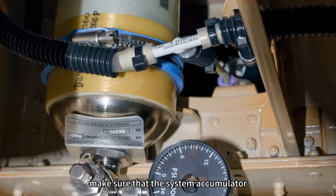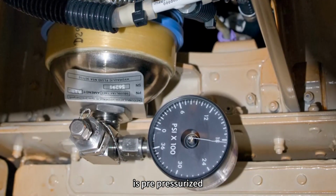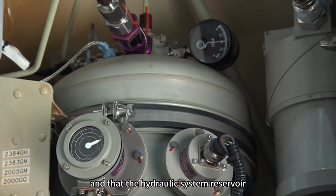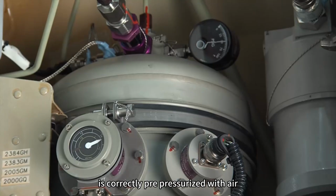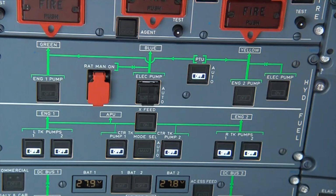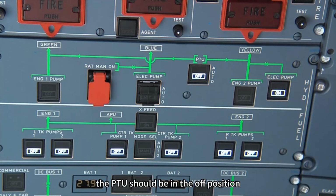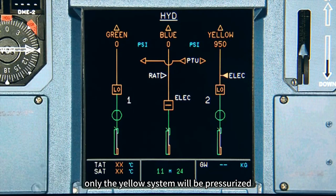Make sure that the system accumulator is pre-pressurized to the correct value and that the hydraulic system reservoir is correctly pre-pressurized with air. Pressurize the yellow hydraulic circuit with the yellow electric pump. The PTU should be in the off position to make sure only the yellow system will be pressurized.